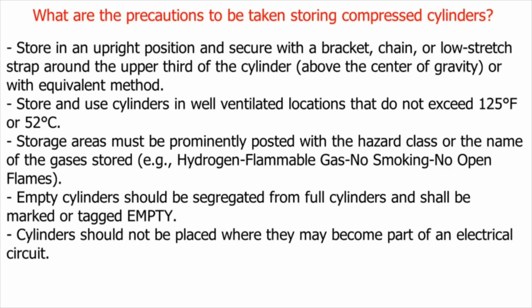Store in an upright position and secure with a bracket, chain, or low stretch strap around the upper third of the cylinder, above the center of gravity, or with equivalent method. Store and use cylinders in well-ventilated locations that do not exceed 125 degrees Fahrenheit or 52 degrees Celsius.